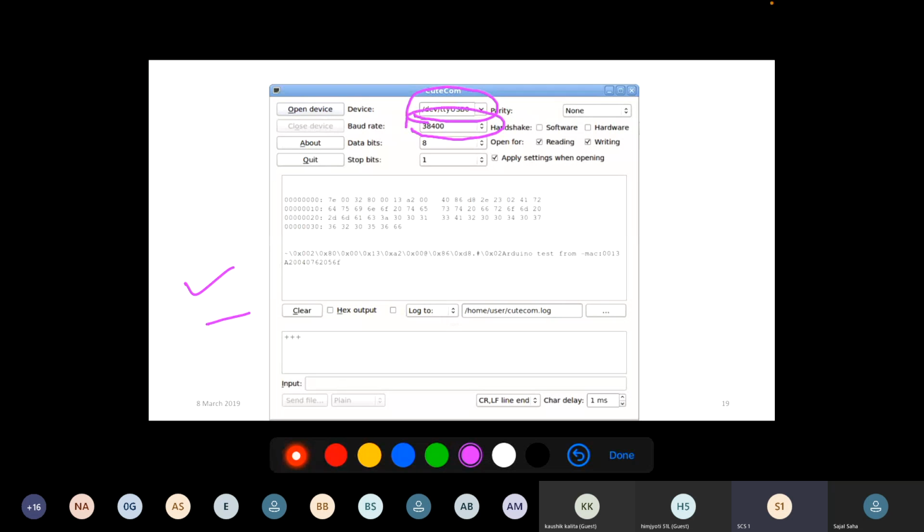Baud rate and bit rate are a little bit different. 38,400 means actually 38 kbps. So at 38 kbps speed, it is getting the data. And what is the data format? You can see the data format is like this. It is written in hexadecimal, and that hexadecimal data will be converted to actual numeric, decimal data to get your data. Is this clear? How you can fetch the data through TinyOS from the Mica motes sensors? This is basically the interface.